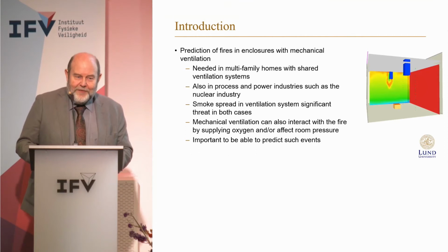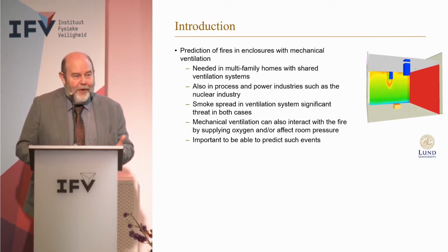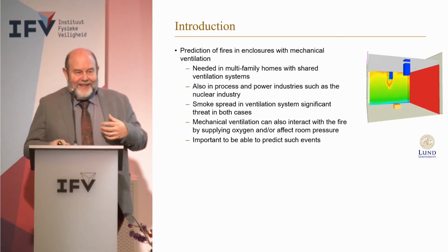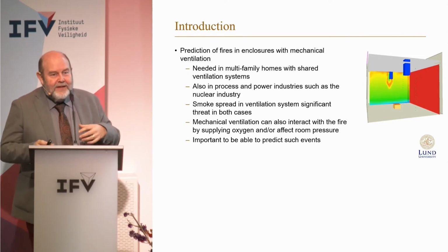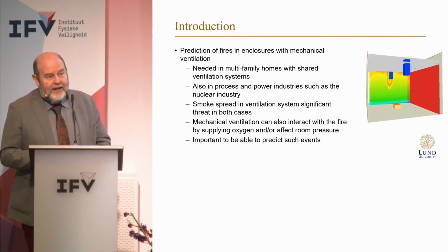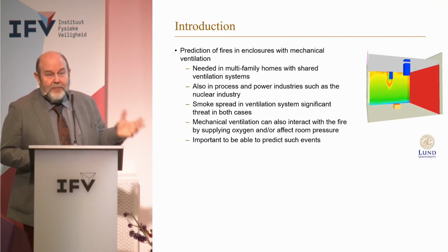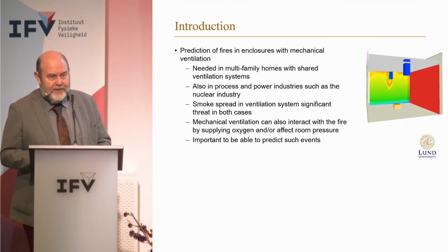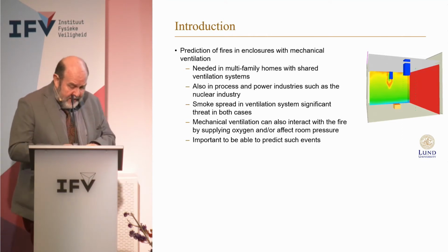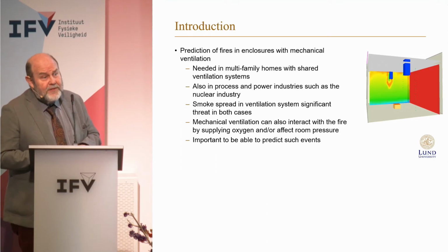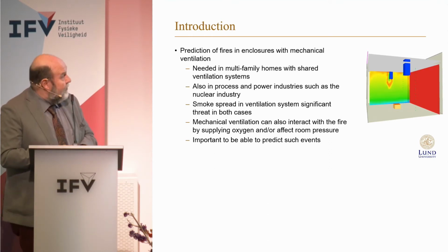And what does that mean for the fire, of course, you will say? Well, you don't have enough oxygen anymore. So the fire somehow will start to starve and to reduce. You will get an underventilated fire, and then, depending on the type of extraction and inlet and outlet ventilation, you can get a situation where this is going back and forth. It's like a breathing fire. In one case, it can also be that it just starves because the oxygen is gone. And that's something where a lot of experiments have been done in this project, which I will explain about.